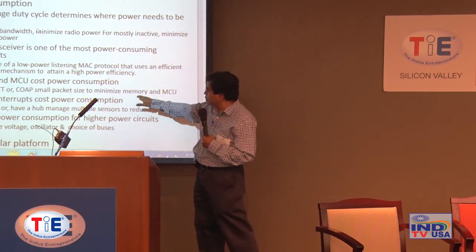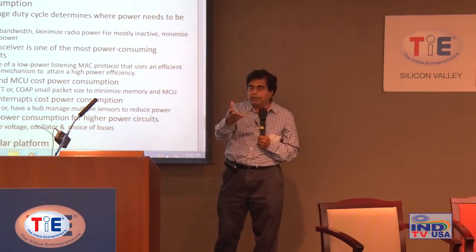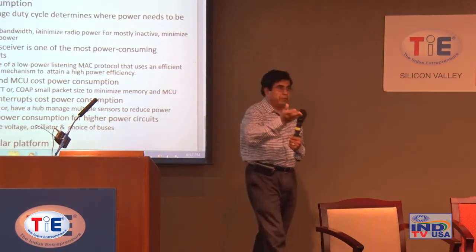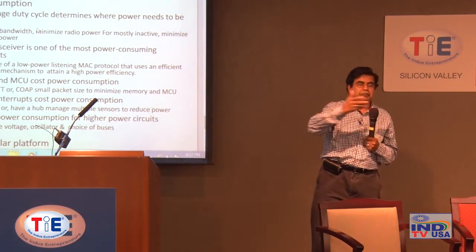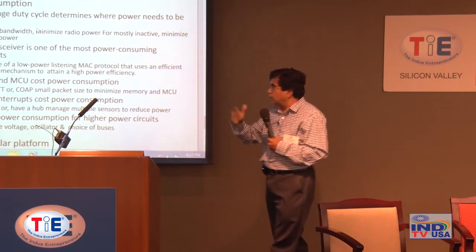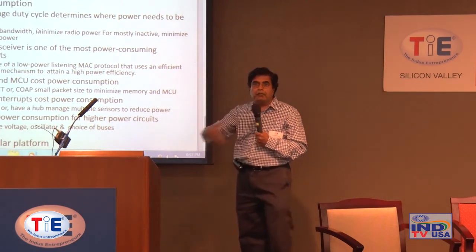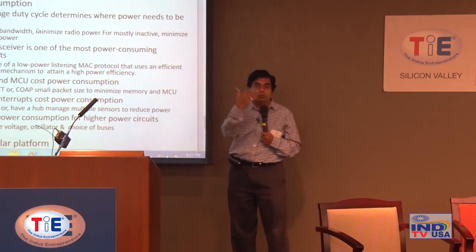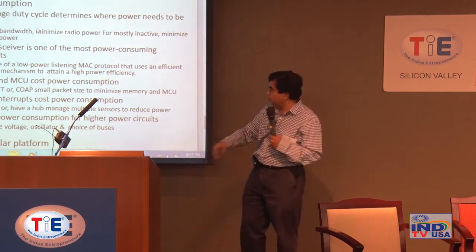So if we use a SoC with a small 64 kilobyte memory, then it's probably a good idea to use MQTT or CoAP. But you will not find a lot of different servers to use it, so you have to put that particular code in yourself. With HTTP REST, you will find a server easily, an Apache server can do it, but this requires some more work on your part to find a particular server.